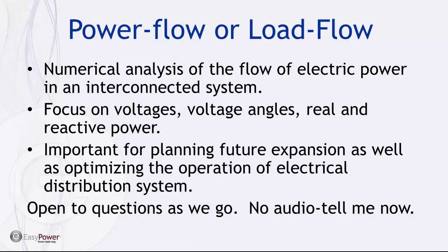It's a combination of calculating the DC resistance and the reactive impedance and the resulting current when an alternating current voltage is applied to that impedance, and then the reiteration until you get a resolved numerical solution that solves all the equations simultaneously.